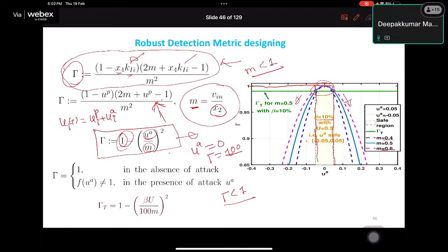Yeah, of course. What I explained was in a very idealistic scenario, just to give you the essence or feel of droop. But lines will have their own impedance, and that will definitely affect it. In fact, the converter on the line with higher resistance will contribute less, because its terminal voltage will be less. Even if two sources are giving the same current, if one has a higher resistance, its terminal voltage will be less, so that source with a higher line resistance will contribute less to the power. That is bound to happen.